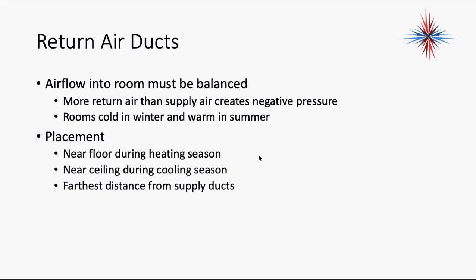Fire situations, for example. If there's a house fire and there's smoke in a hallway, if you have a negative pressure in a bedroom, that smoke is being pulled into that bedroom. So our ideal condition is either to have an equal pressure throughout all spaces in a building or a positive pressure. That's our goal.